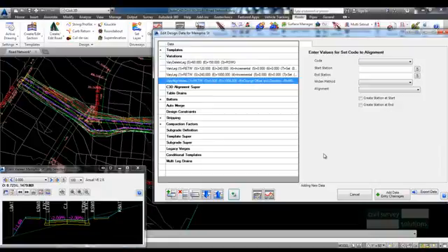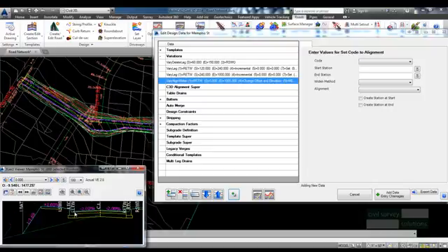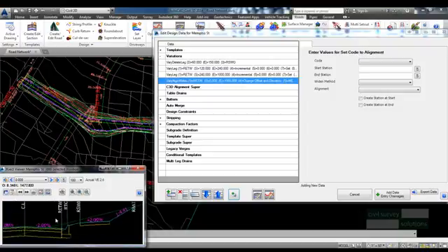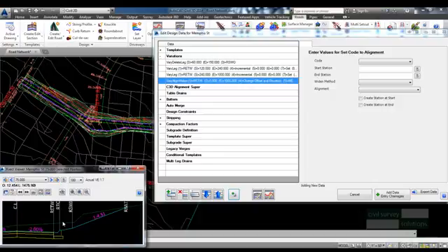For this example, it is desired to have a retaining wall located behind the back of the curb. To reduce the depth of cut fill at the property boundary on the right side of Memphis Street, near the start of the road, the retaining wall will extend from station 60 to station 240 and be created from two sections inserted into the cross-section.